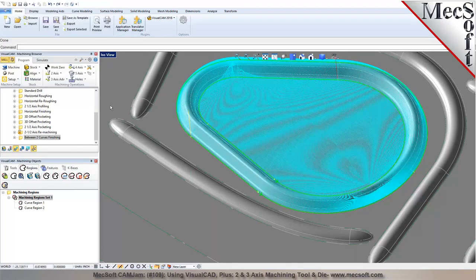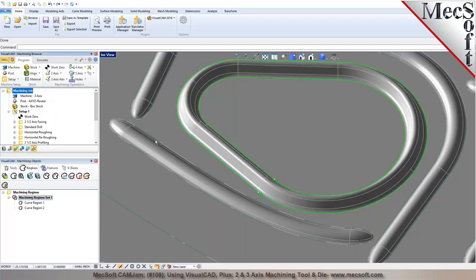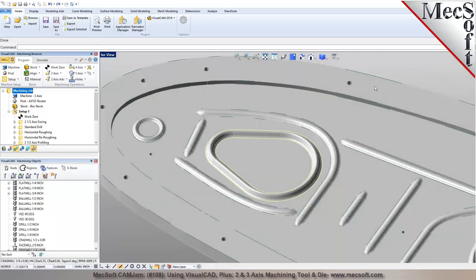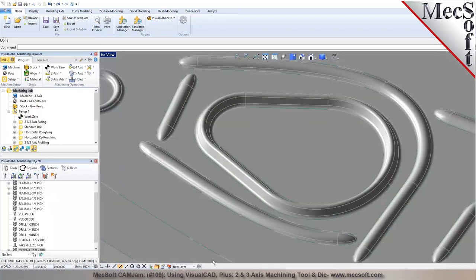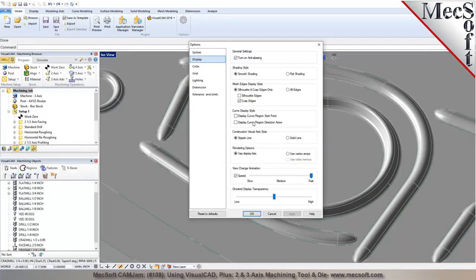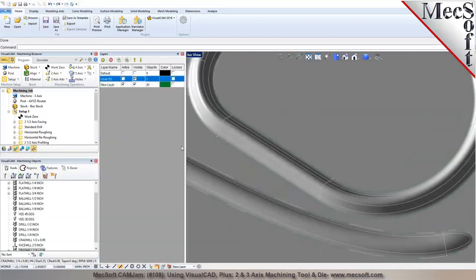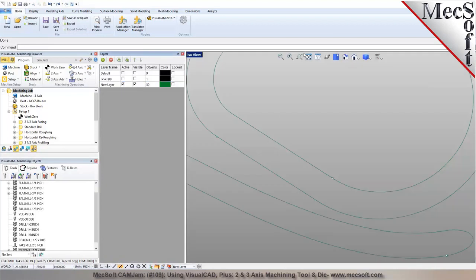Okay, I noticed on your right, on the upper left-hand corner of that pocket, the curves are twisted in that region, so I need to go back and redo the curve regions that are a little bit twisted. Let me show you how I can correct them, and you can go back and machine it very efficiently here. If you notice these curves in here, each of these curves has a direction and a start point. So I can display those curve directions and start points in here. Let me go back to this layer and hide this one right here.